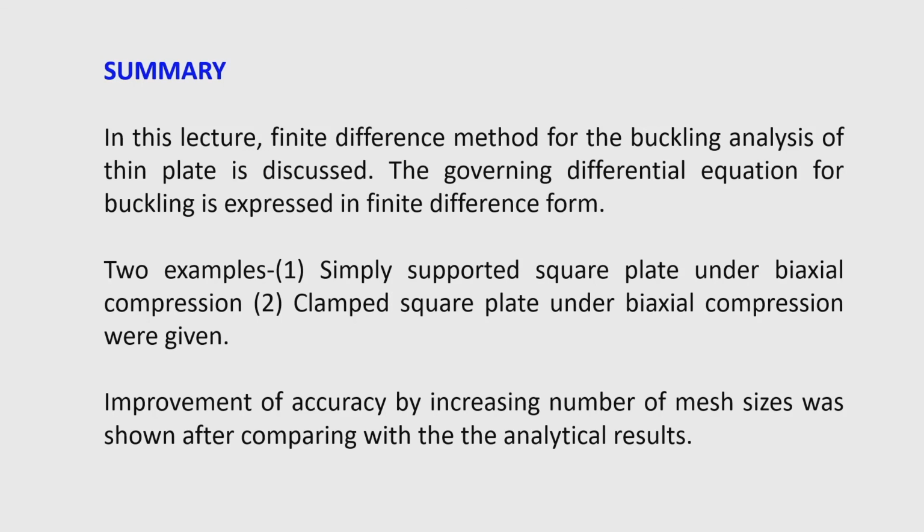One problem is a simply supported square plate under biaxial compression, and the second problem is a clamped square plate, the plate which is also square, but the edges are clamped and also under equal biaxial compression. Improvement of accuracy by increasing the number of mesh size was shown after comparing with the analytical results. Okay, thank you very much.